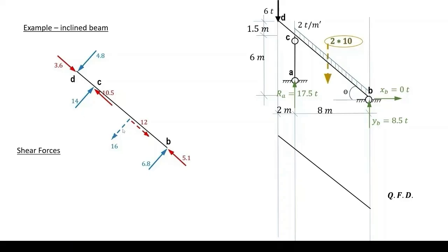Also, the 16 tons component of distributed force makes us expect an inclined diagram in the part CB. Starting from D, our left hand side has a 4.8 tons shear heading downwards, and therefore this is the negative shear and will be plotted below the center line.